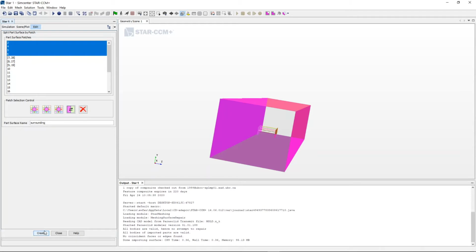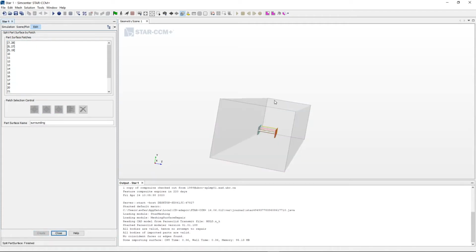Since this is a rear wing, I'm just floating it in the middle of the air. However, if you were doing like a car or something low to the ground, such as a diffuser, you would unselect this bottom face and create a different face for it. That way you can assign it to a different region.